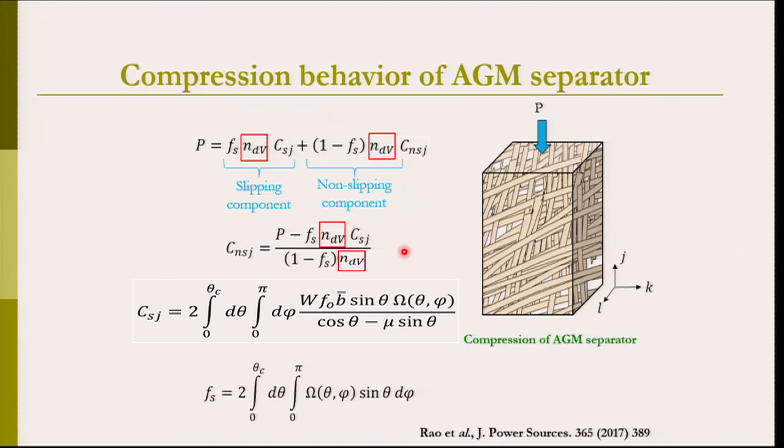So, you can see the non-slipping contact here is the component of fibers that are going to bend between the two successive fiber to fiber contacts. So, this is the average load which is being transferred to the fibers in the non-slipping contact, which can lead to the bending deformation of fibers within the meso domain NdV.